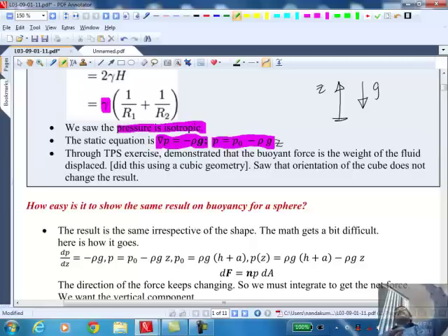So if I have a pen in air, does it experience buoyancy force? Yeah. In principle it does, right? But is it going to be strong? Why? Because density of air is very small. Buoyancy force is the weight of the fluid displaced. So if I know the volume of this pen, I can calculate the weight of air occupied by that pen. That is the fluid that is displaced. Because air density is so small, buoyancy force here is very low. So if I drop it, its weight is so much that it will fall.